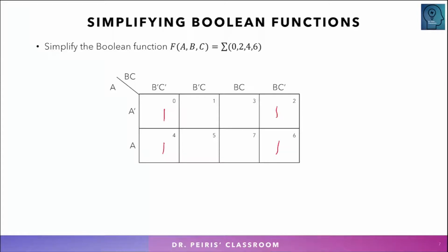When I explained, I mentioned one special thing about adjacent columns. We consider the first column and the fourth column as adjacent, which means you can make a larger group from these two columns. This column and this column are considered adjacent. That means we can make a group like this. So they are grouped into one large circle. So all four correspond to one large circle. So it is only a single group here.